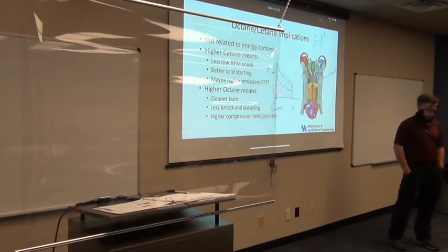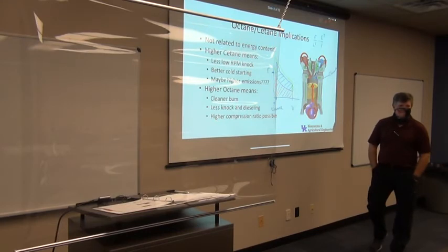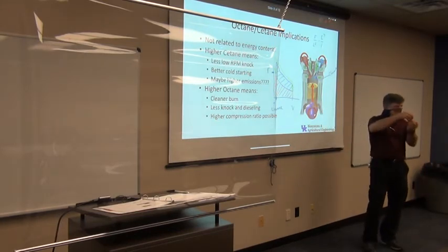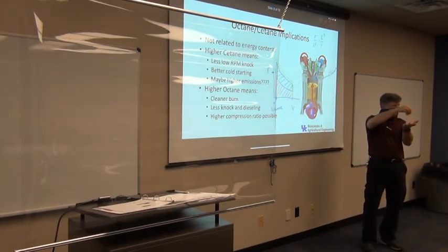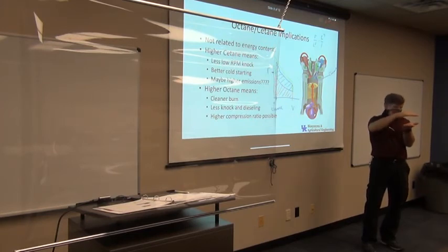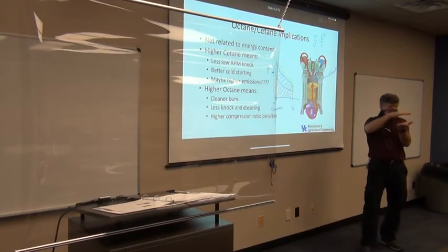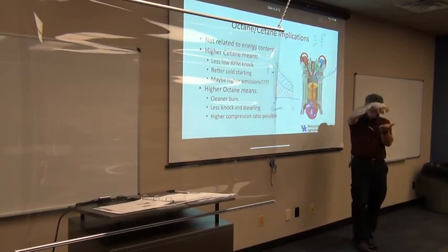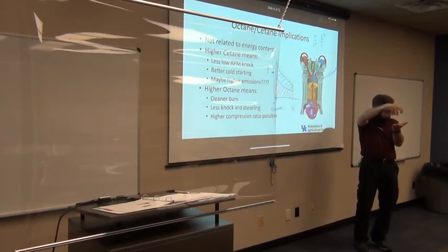Really? Can it burn too fast? So think about that. There's a burning front. When I inject the fuel, or when I light the spark in that space above the piston, there is a burning front. That flame is going to start, and you're going to have a burning front that moves across that space and moves out through that space. And it originates from either the spark or from where that fuel is injected in there.